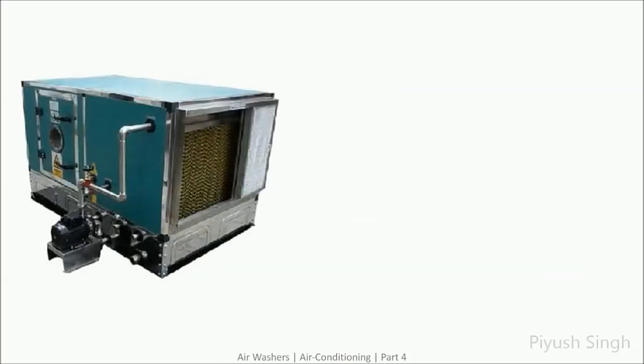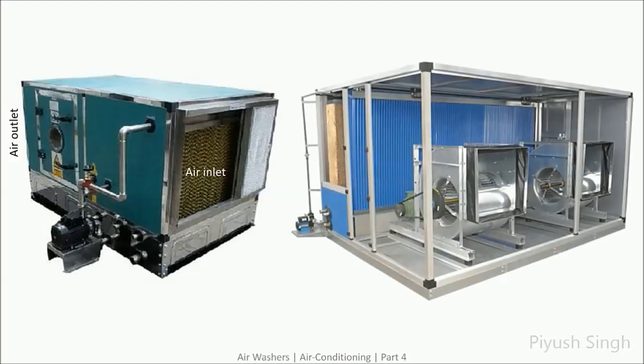Here is a photograph of an air washer. Typical commercial air washers are enclosed, room-like spray chambers through which air being conditioned is drawn. These air washers are usually box-shaped with insulated enclosures on four sides. The other two faces are inlet and outlet for air. The floors are formed by large shallow water reservoirs or sump tanks whose bottoms are often sloped to aid drainage and sludge removal. Here is a photograph of an air washer with the enclosures removed.